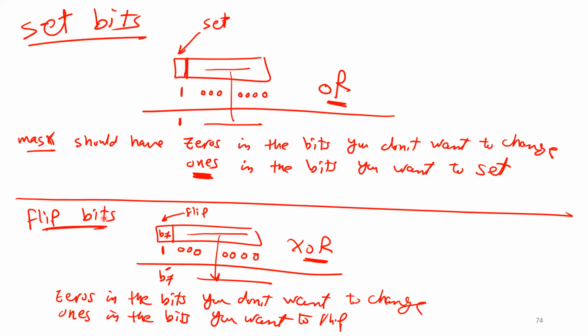Again, guys, please don't be confused. Here in this example, I just gave an example on 1 bit, but you can use it on more than 1 bit for sure, right? So in the same instruction, if you want to set 2 bits, you don't need to use 2 ORs. So 1 OR, and then you can put 1 1.